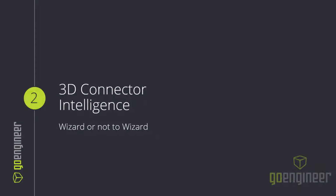It could be a cube that you drew, it could be something you downloaded. I do recommend that you clean it up. Make sure you do an import diagnostics on it, make sure that it is a stable file, not something that's half surface body or something like that. Sometimes it's faster to redraw it than it is to fix a part. And then my second statement on this slide is, do we use the wizard or not use the wizard to add connection points? And I'll talk to that here in a moment.